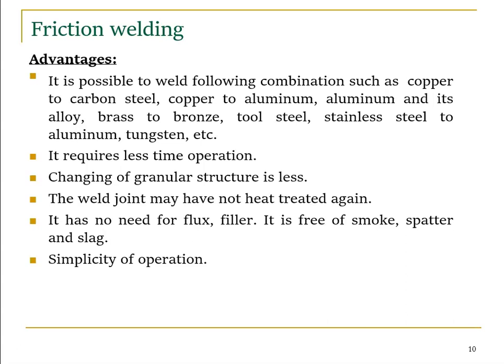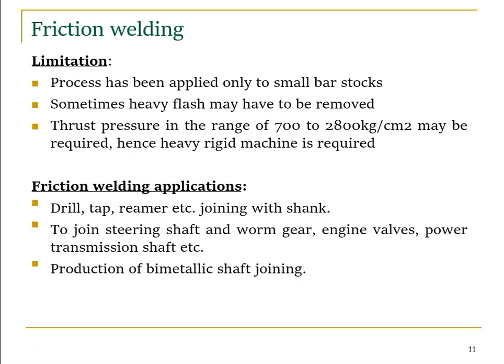The weld joint may not have to be heat treated again. So there is no need for heat treatment again or other secondary processes; they are not required. It has no need for flux or filler, and it is free from smoke, spatter and slag. And it has simplicity of operation, right? So these are some of the advantages, right? The next one is limitations.